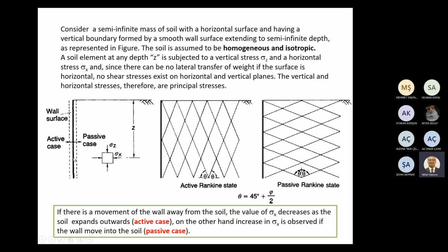Actually, when this wall moves away from the soil, of course, lateral stress in horizontal direction, or sigma x, should decrease, because soil here will expand laterally.